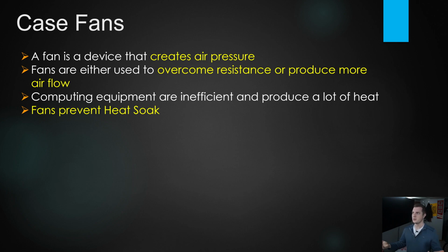Okay? Regardless of what the environment is for the server or the consumer, you're trying to prevent heat soak. And what that is, components are going to generate heat. And then there is convection, but it's a very weak force. So if you have a bunch of heat in an area that's not going to get rid of that heat very quickly, it's essentially going to create an environment for itself, and it's going to overheat itself around the components that are making heat. This is called heat soak.